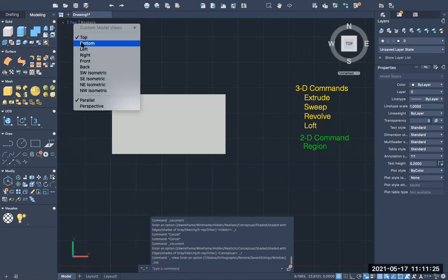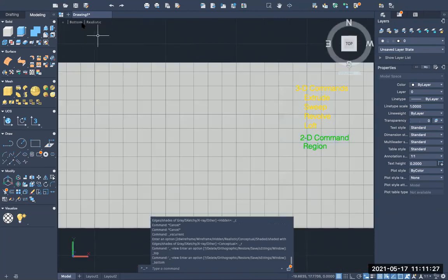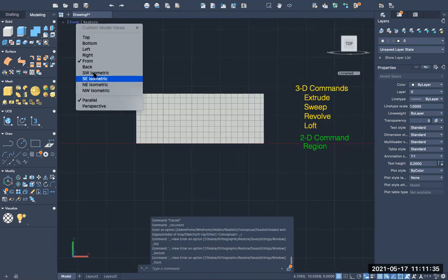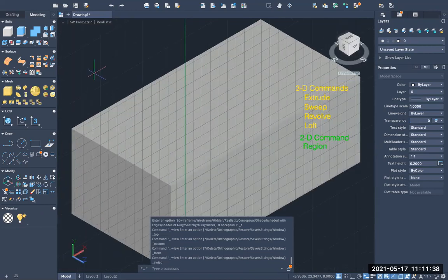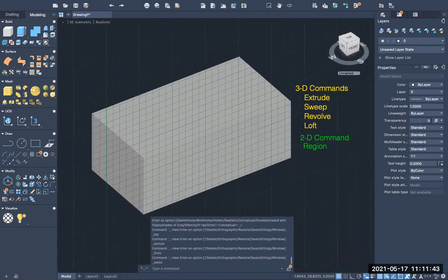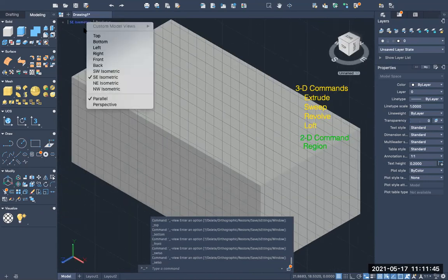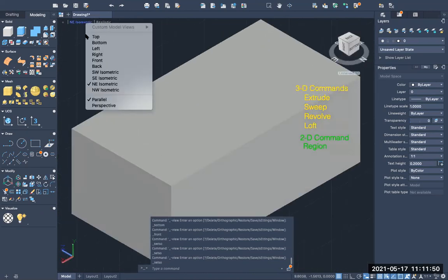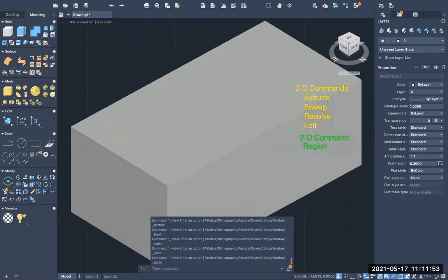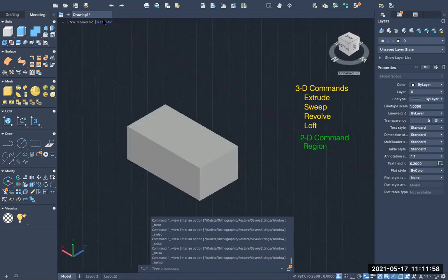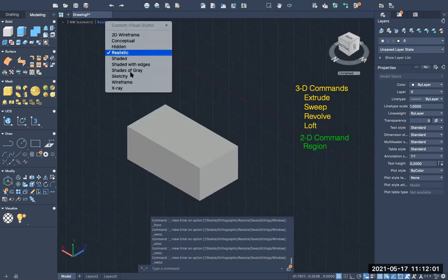Now, a different bottom view, if you want to see, you can click that. Front view, so you can swipe between those different views. Okay, this is your isometric view also. Southwest isometric, southeast isometric. Similarly, you will be having northeast and northwest. Okay, so any one of the isometric views you can keep. This is regarding how to change the view, how to change its viewing style.